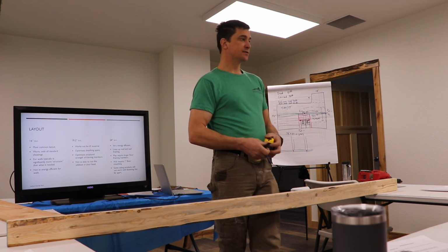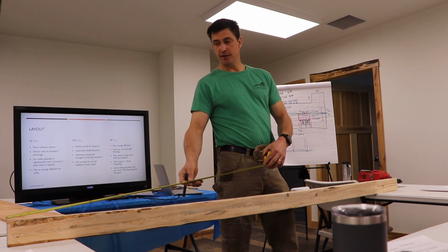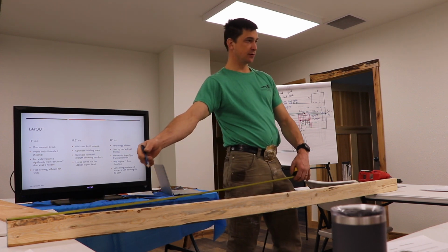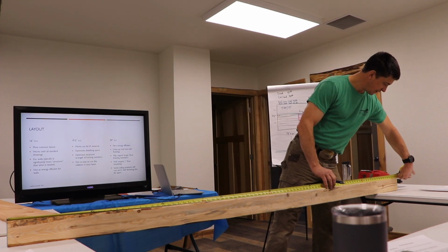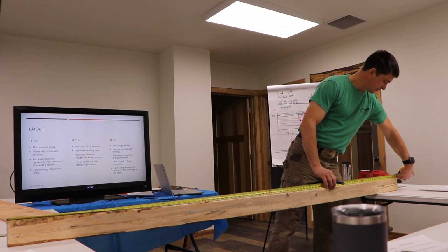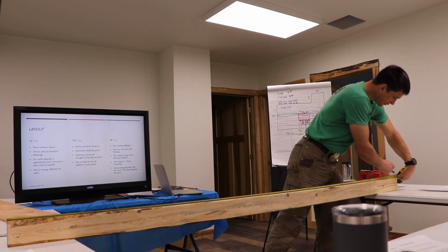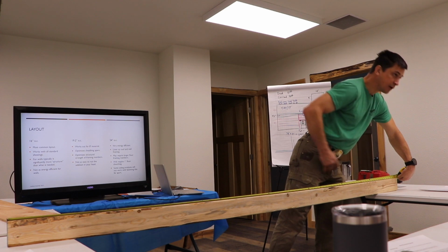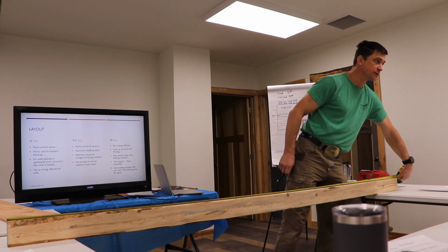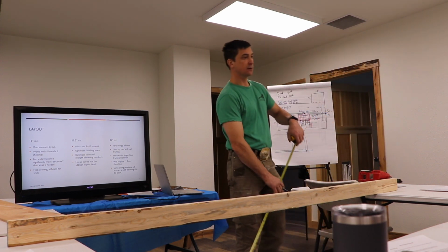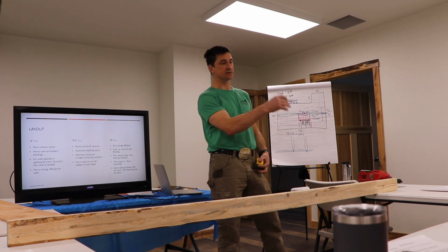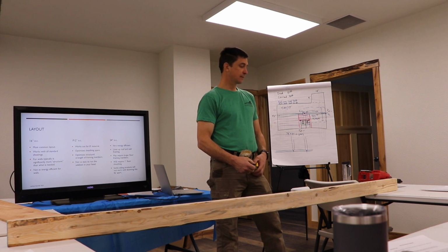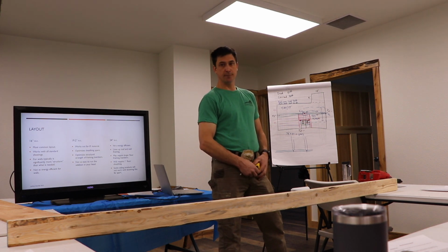It's so that if I'm marking 3/4 short of my center line, when I get to the end, I can put a mark for my last stud, right? Yeah. If I'm going 3/4 past, there's no wood for me to mark it at 96 3/4. That's the only reason why we would typically go to the short side versus the long side. So, okay?